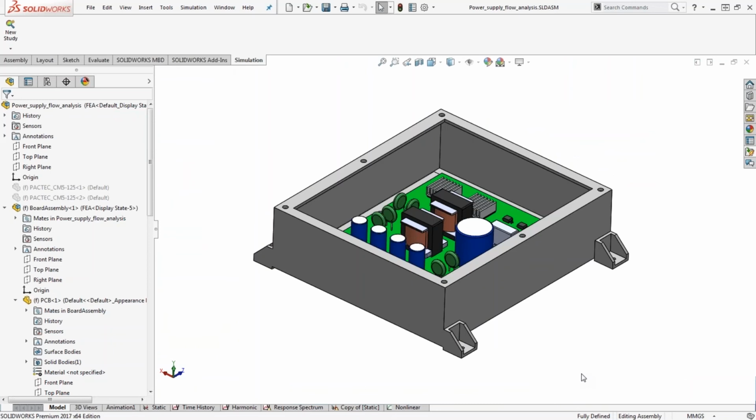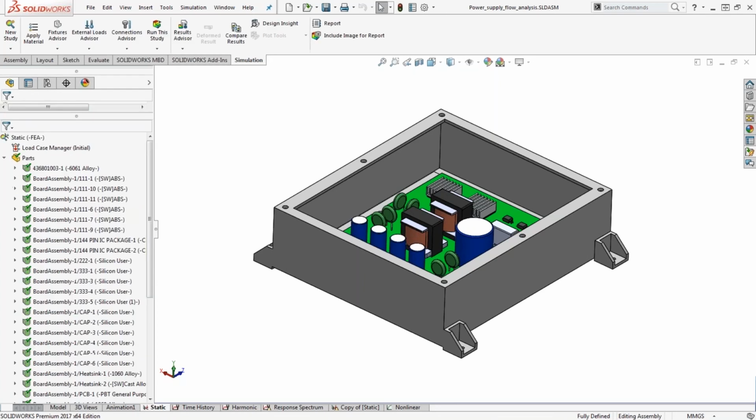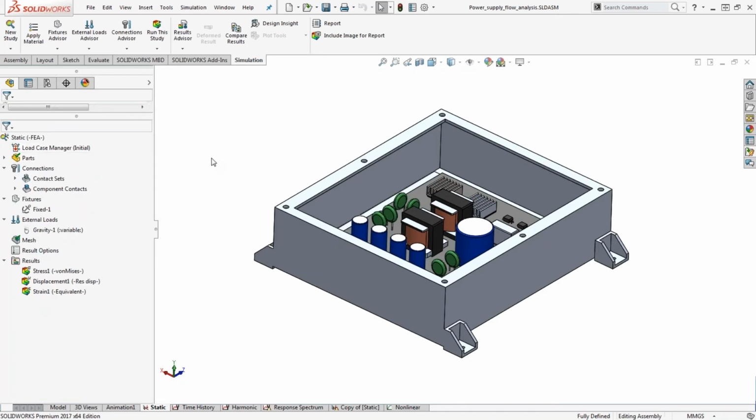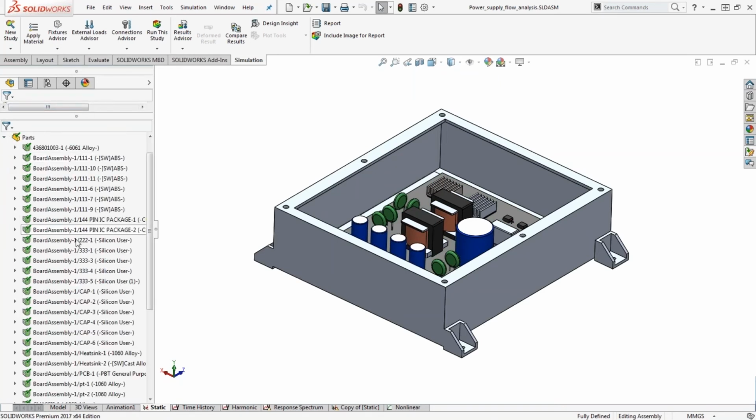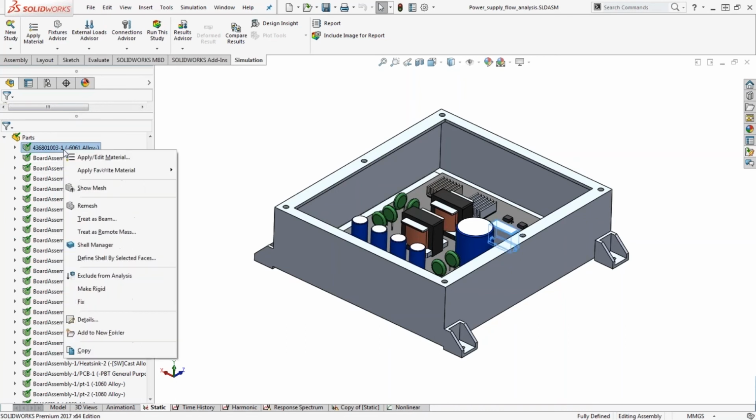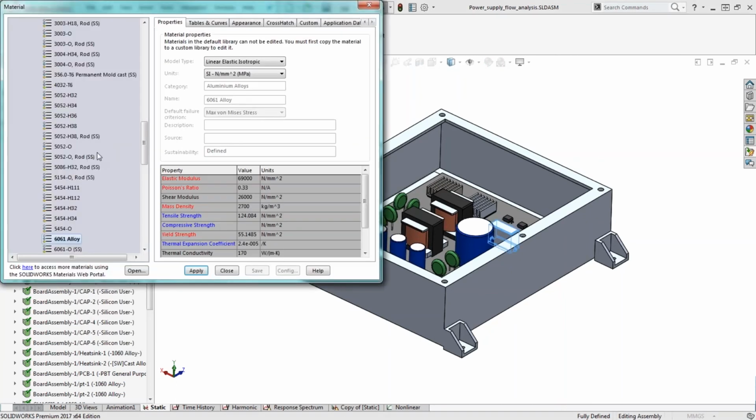Okay, so if we were to narrow this down by product, then with SOLIDWORKS Simulation Standard, we always want to start off with the linear static assembly or linear static study. The thing to be aware of is the assumptions we take within that. The material that we apply to our parts is always going to behave linear elastically here, so we have no way of defining what's going to happen within the plastic range or post-yield. So we assume that the displacements we're going to see are small, versus large displacements where things may be going into yield. So we can't really account for permanent deformation within the linear static.